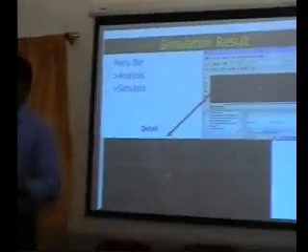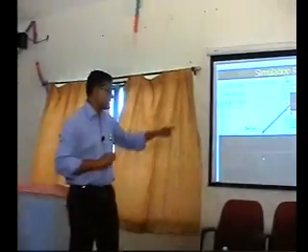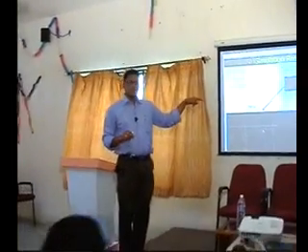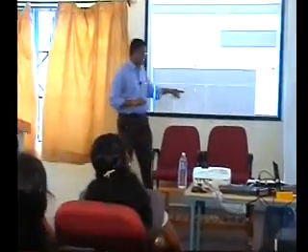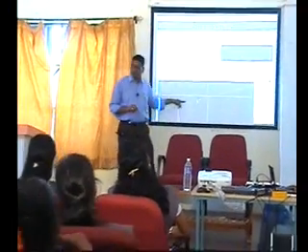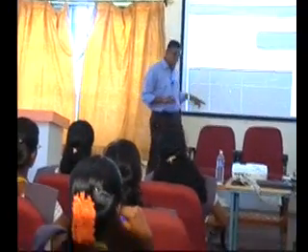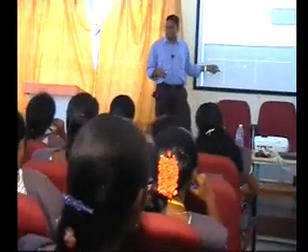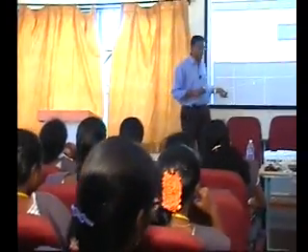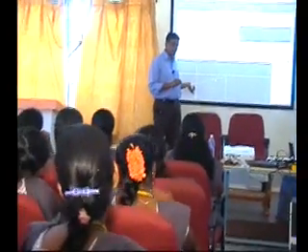After placing the probes, when you simulate, you will get a black color window like this. This black color window is a graphical user interface and it is called a trace. What do you call it? Trace. So the x-axis you can choose, the y-axis variable also you can choose. Understand? The x-axis need not always be time. It can be voltage also.